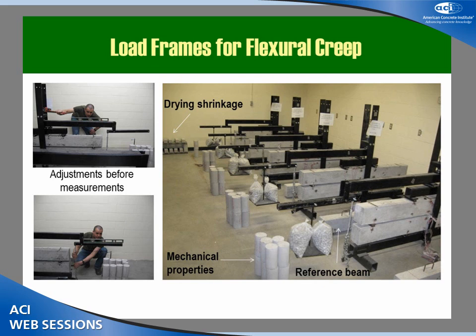All right, the last part, and I'm not going to show you a lot of results, but this is just coming very, very fresh out of our testing program, is a new type of behavior that is flexure creep. So we're all familiar with creep under compression, but this is creep under tension, and not only under tension, but under flexure.